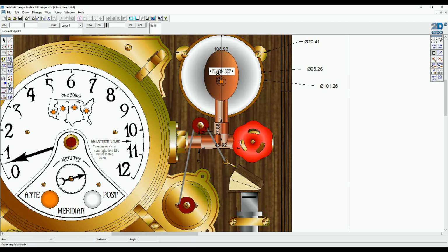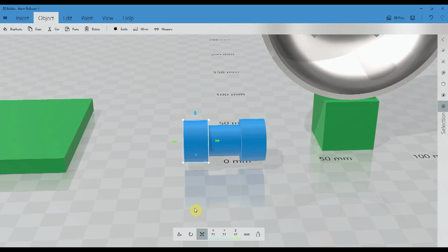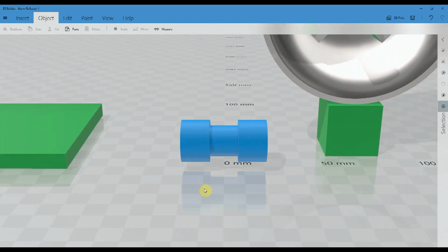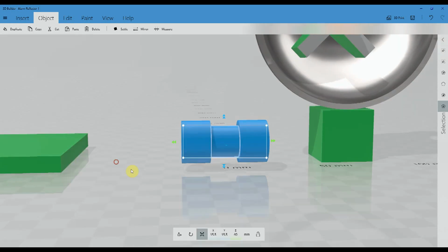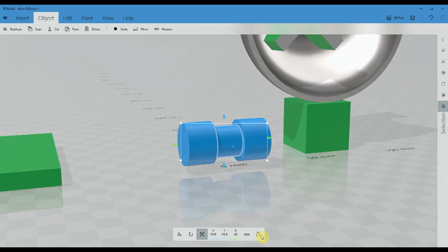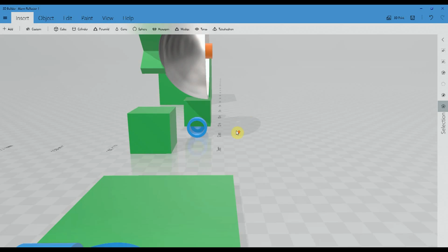So here I'm just measuring, taking dimensions to find out how large this connection needs to be. The very important thing about it is that I need to be able to have it the right size to push or glue in normal 15mm copper pipe by either side. I also need a hole through the middle so that I can poke the wires for the encoder and other bits and pieces. Right, so fiddle around with that for ages and then hollow out bits with the subtract tool. We've ended up with this.